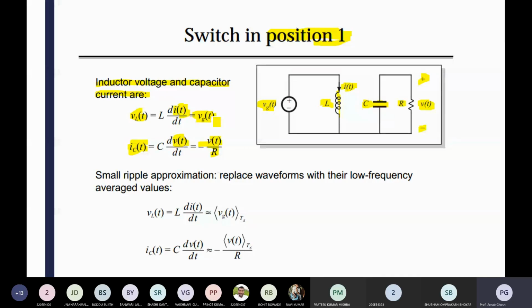Eigenvalues are there. If you change the value of resistance R, how do those eigenvalues change? You can also plot the eigenvalue against the variable value. You can use a for loop. By changing the value of R, see how the eigenvalue is changing. You can place it over here. The eigenvalues are changing, and the inductor current for each instant, as you change the value of R.